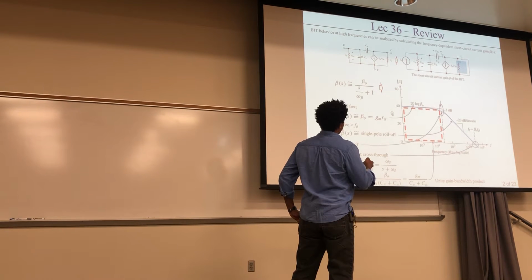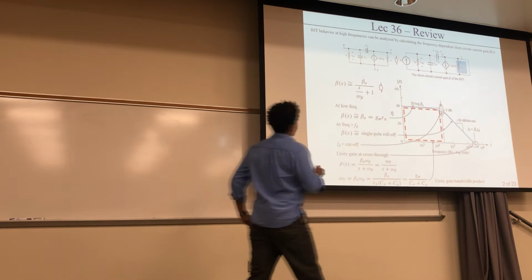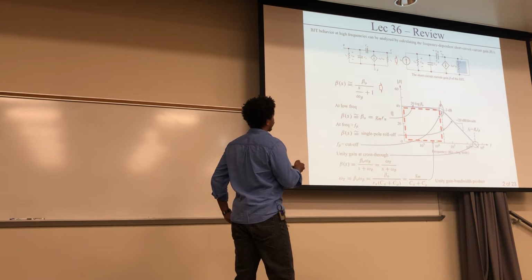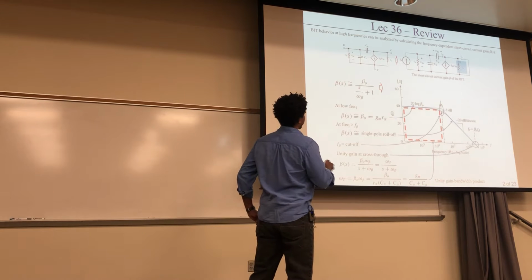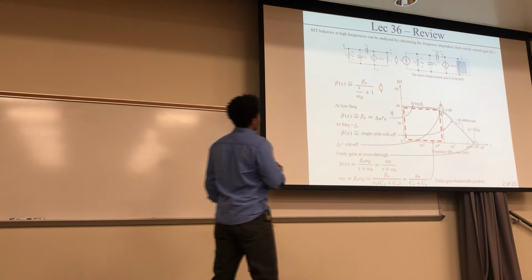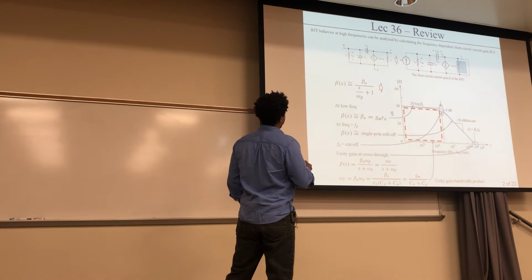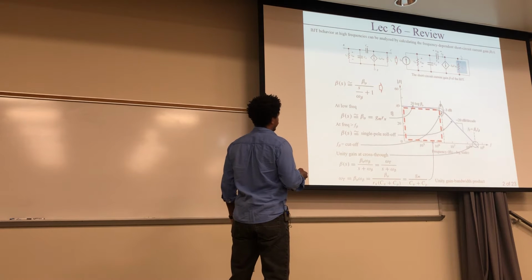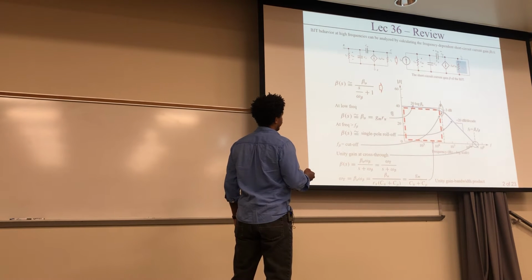To analyze that, we use this short circuit method to determine the gain beta. We apply the short circuit right here for that current, and we also apply an input current right here. That's the difference going from here to over here. What we found is that we're able to determine this current gain, and we do a Bode plot of it. The blue line is this equation.